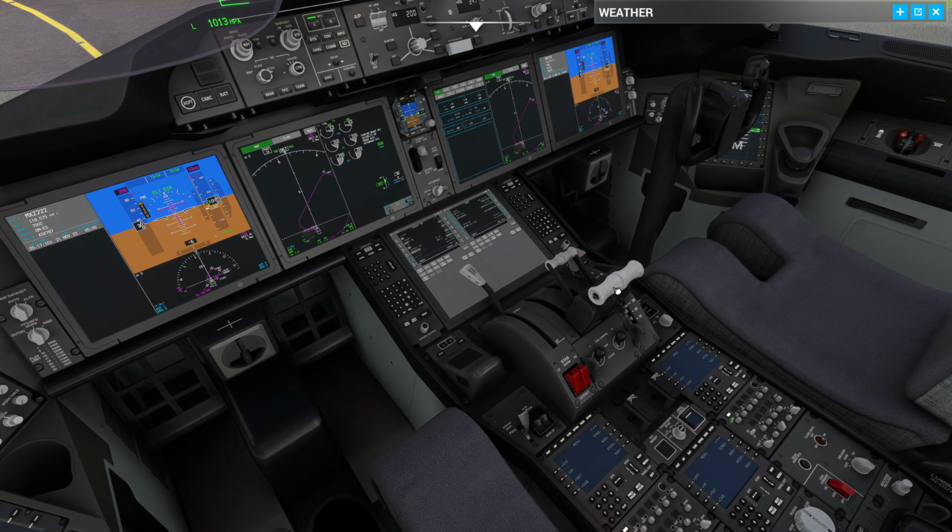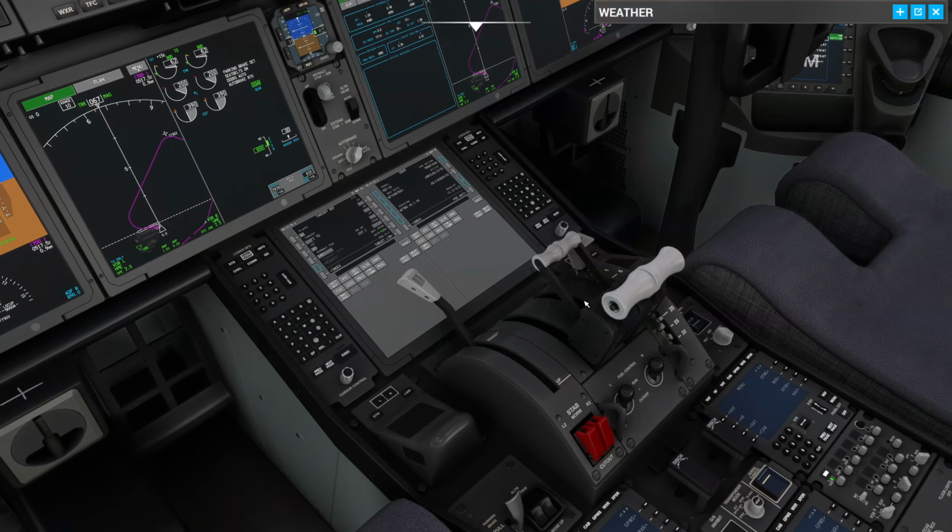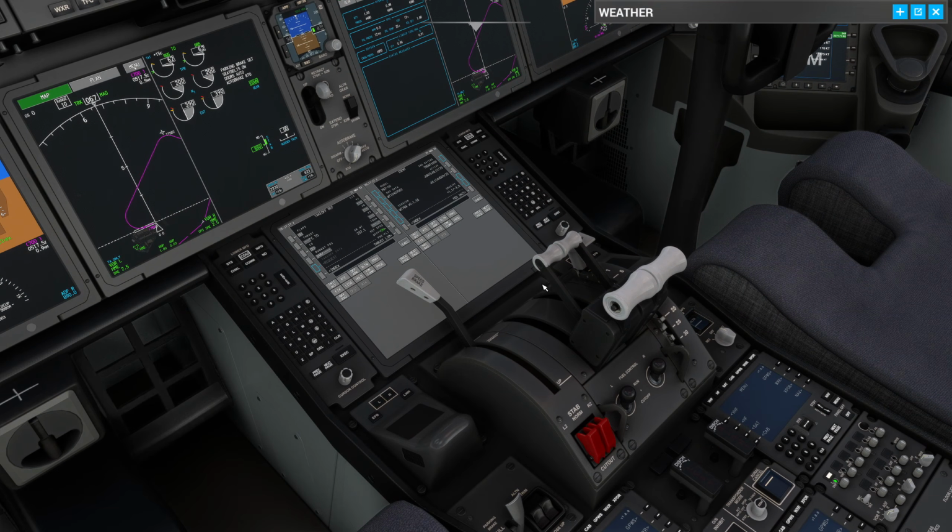Remember, this is a Boeing, so unlike the Airbus, we have direct control over these thrust levers during the takeoff roll. We can finely tune that power, so you could just squeeze a bit more power on if you wanted to. You don't have to go the full way, unlike the Airbus where you would just click straight through to TOGA most likely when you wanted it.